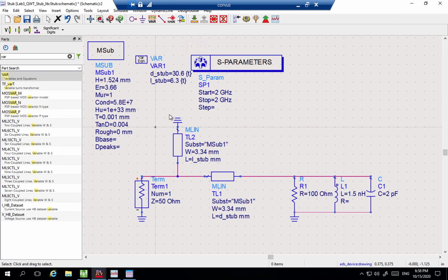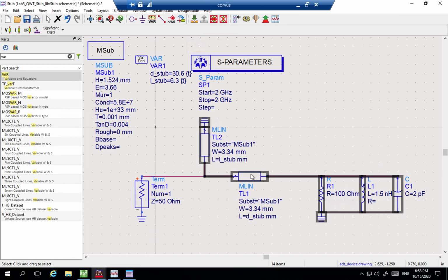What do you expect to happen? Do you expect the position to change? Let's say we were exactly in the center of the Smith chart. If you answered no, that would be right, because once we have an input impedance of 50 ohms, if you add another 50 ohm line, that doesn't change it.